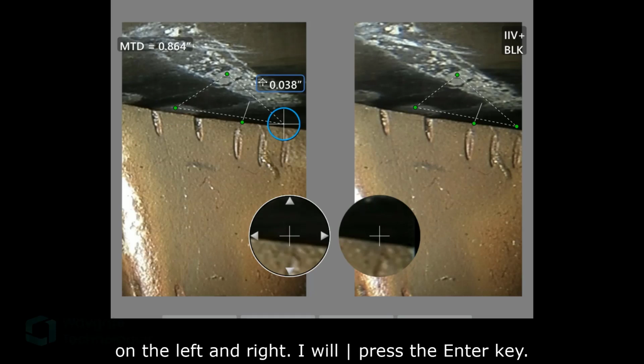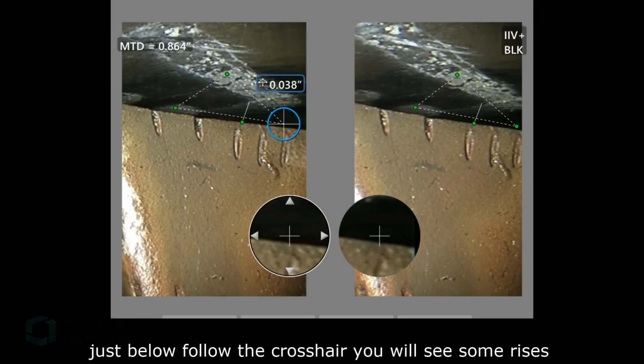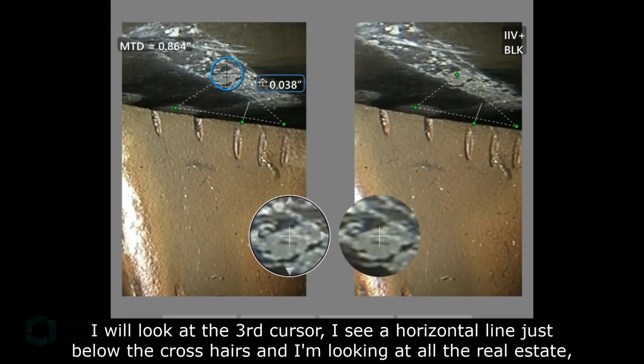I will press the enter key. I'm looking around there, and the references that I have are the landmarks on the blade tip just below the crosshair. You'll see some rises just to the right. You'll see a cooling hole just below it. Looks like a fairly decent match. I'll look at the third cursor.